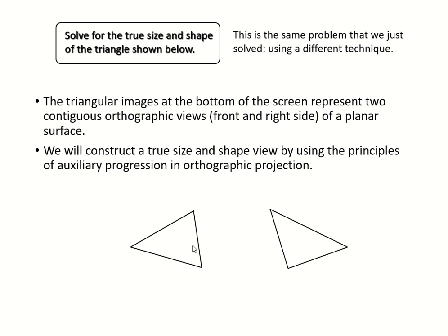So you have two views, front and right. And we think about inclined or oblique. It's definitely not inclined, it is oblique planes that you're dealing with, because you don't have the edge view in any of the given views. You try to project it by yourself from here and still you don't have it. We usually draw the first fold line or reference plane in between the two views, and you look for parallel lines to it. We don't see it.